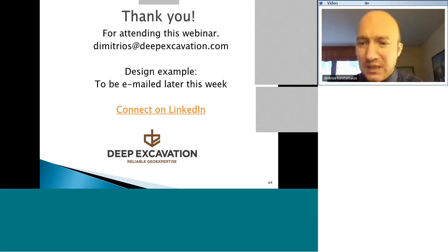Is SPT, okay, the modulus of elasticity for each load step in laboratory tests is different. So from your point of view, is SPT more relevant? SPT, from my point of view, doesn't measure really a lot of things. Of course, if you have sand or rock, you have to use SPT and make adjustments. So you have to adjust your modulus of elasticity with different stresses, and that's why I like models that do that.